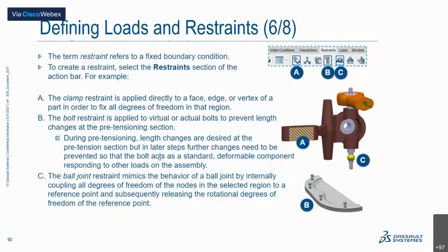And ball joint is one more. These are a few which are generally used, so the commands have been present there. It basically mimics the behavior of a ball joint component itself. So if you have a ball joint model, then you can use the ball joint restraints.